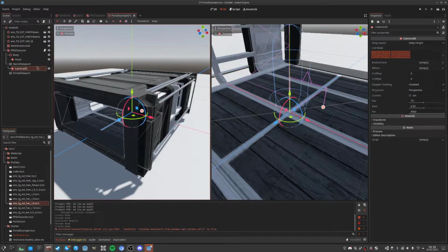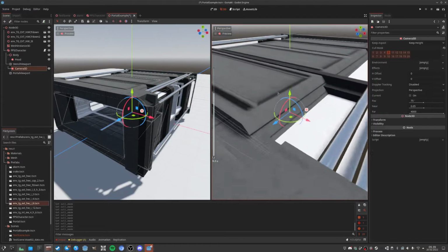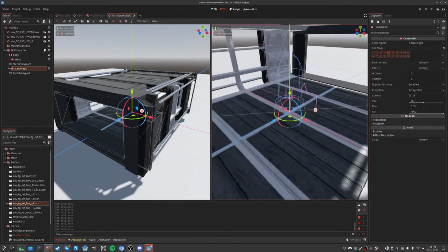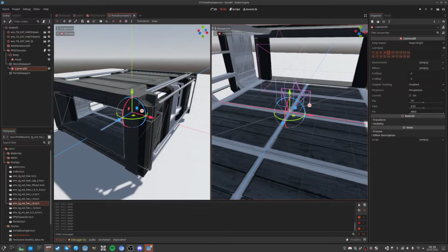And in the stencil viewport we need a camera, and this camera is special in that we only want to render one layer on this camera, and we don't want any lighting or shading or anything like that. We're going to choose layer 5. So this will be the stencil layer. What's important here is that in the stencil layer we want that image to be black and white. White where the portal is and black where everything else is. In such a way that everything else can block the stencil or the portal itself, so that you don't get a portal standing over everything else. But you will see what I mean.